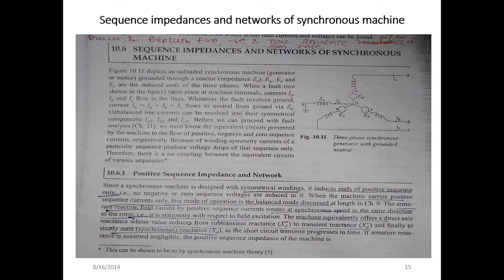See, the word is synchronous machine. That means here you can consider the synchronous generator or synchronous motor. That's why this is the generalized term, synchronous machine. Here we have to show the sequence impedance and network of the synchronous machine. For example, there is a repeatedly asked question: draw and explain the positive, negative, and zero sequence network for the synchronous machine.